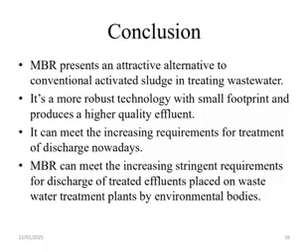So now we have come to the conclusion that MBR or membrane bioreactor technology presents an attractive alternative to the conventional activated sludge process for the treatment of wastewater, as it is a more robust technology with a smaller footprint and it also produces a higher quality effluent. It can also meet the increasing requirements for the treatment of discharge nowadays.